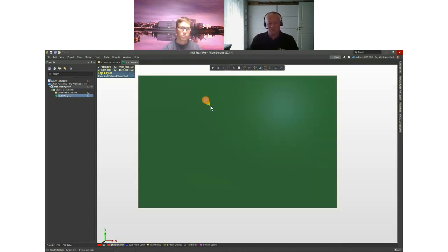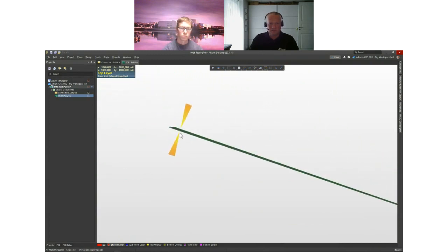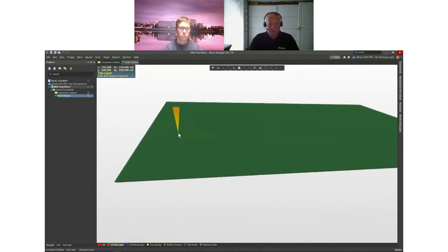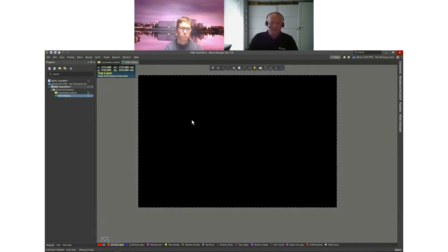If we switch to 3D mode, you can see that I have 2 layers and here some kind of thickness of the PCB also here. Let's quickly change that and actually enable the printed electronics. So in here, I will go to the layer stack manager for that. And in here, we will see the couple layers, the core and so on. And I will then enable the feature called printed electronics. It's a little bit slow today.